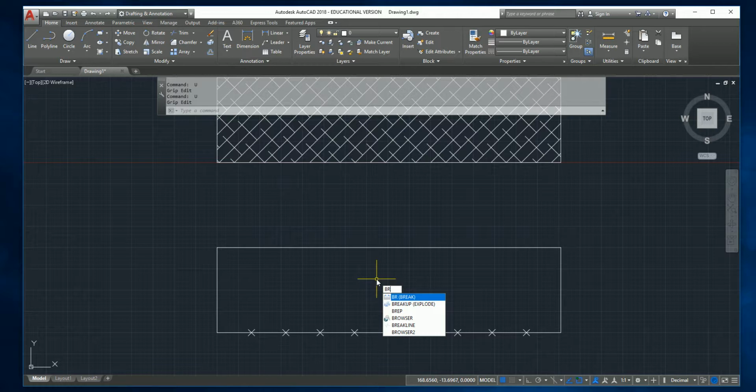That way you'll be able to put in doors and windows. You could always break something and then put the slats in. We're going to draw a window right now. You can use whatever you want for the window symbol, hatch, whatever. A window could be done as a block, as a series of lines, or as a parametric. The slided lines are what you're thinking of in an elevational view, where you'd have the lines to show glazing. Okay.